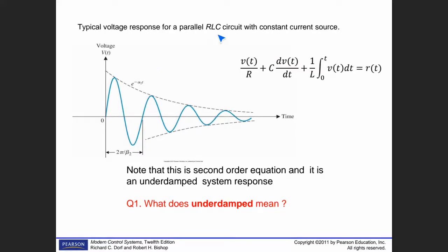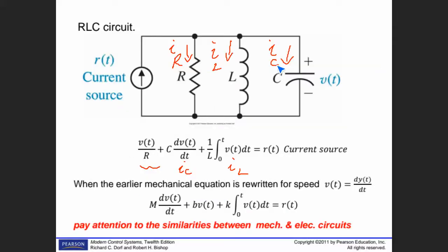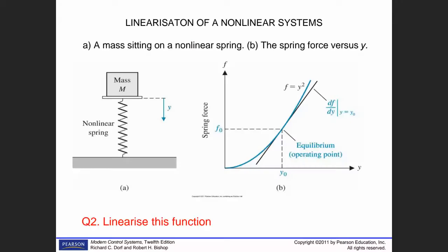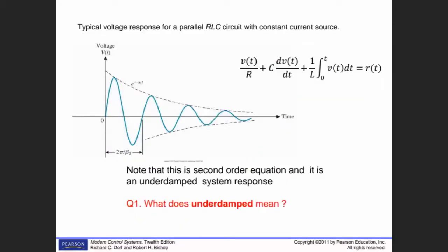When you solve those kinds of equations, this for example is one parallel RLC network. That is the voltage. Geri dönüyorum, come back. So that is the voltage here, V. So voltage divided by R. When you solve it, of course this is a second order differential equation. You are getting the derivative of the current as well, and then you solve it.